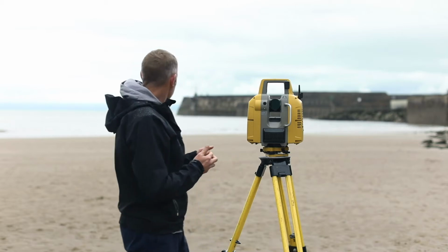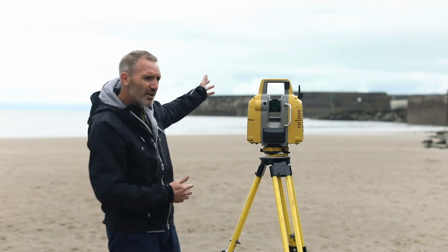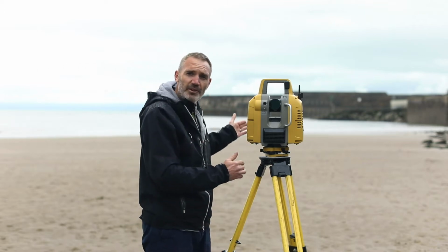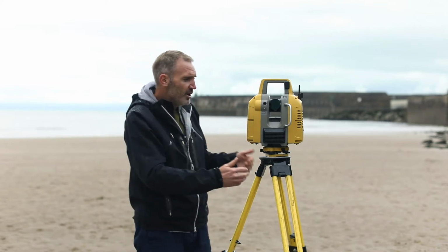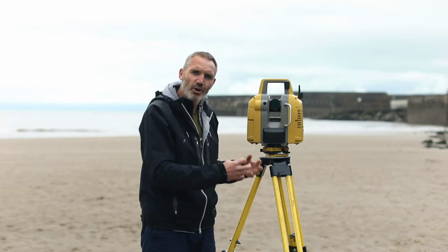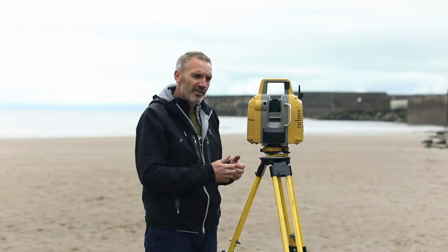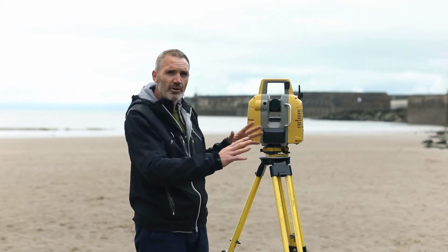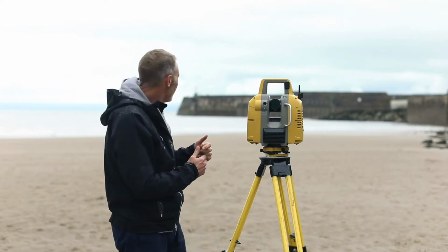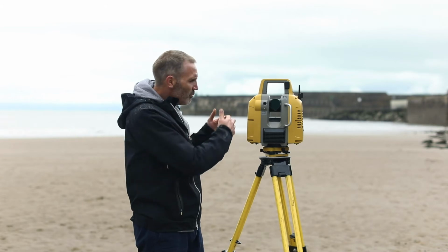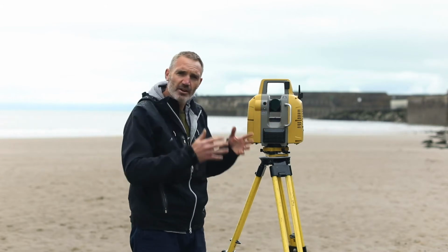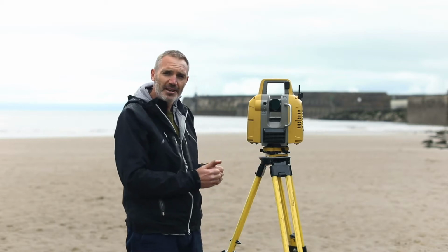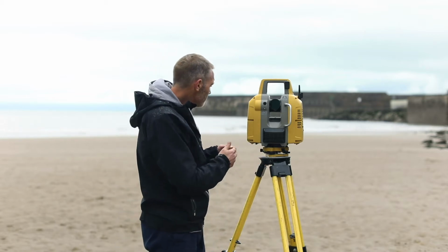So those white signs on the breakwater over there will give brighter reflections than the darker bits covered in seaweed. And right at the worst case, if we've got wet rock with black algae on, that may not give any returns at all. But on the whole, this is a very good surface. It's quite bright. And so within the full sphere of that data, we'll get up to 300, maybe 350 if we're lucky, meters of data.